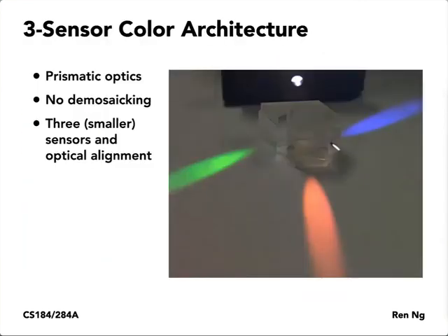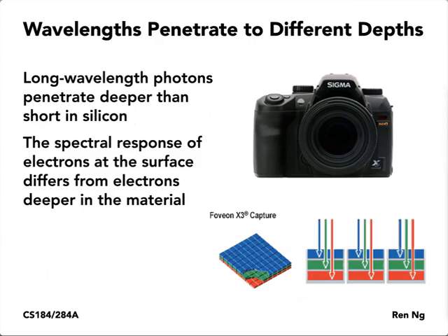Okay, so we got through these topics, some alternative architectures for color that are not as common, the color filter array in front of the image sensor pixels being the most common thing. And then we ended up at dynamic range. So as a whirlwind recap of things we described last time, I described demosaicing last time, so I won't take the time to do it again here today. But basically, the high-level problem is to take the array of color mosaic values, one per pixel, and then figure out how to compute an algorithm to get RGB at every pixel. Okay, so that's the demosaicing process.